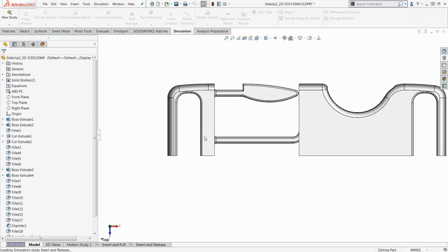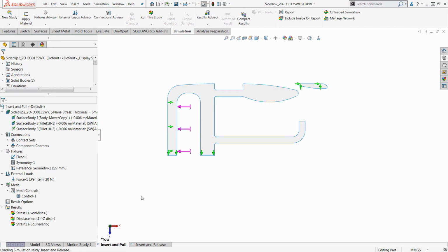Next up, we're going to look at symmetry of your results. A lot of times people use symmetry and it's awesome, right? You get to just run the analysis on half the model. In this case, I've done 2D simplification and I've used symmetry. So my run times are going to be way faster, right? And in this case, I'm doing a nonlinear analysis, and hence I really want to keep that runtime low because I need to run it for multiple steps.